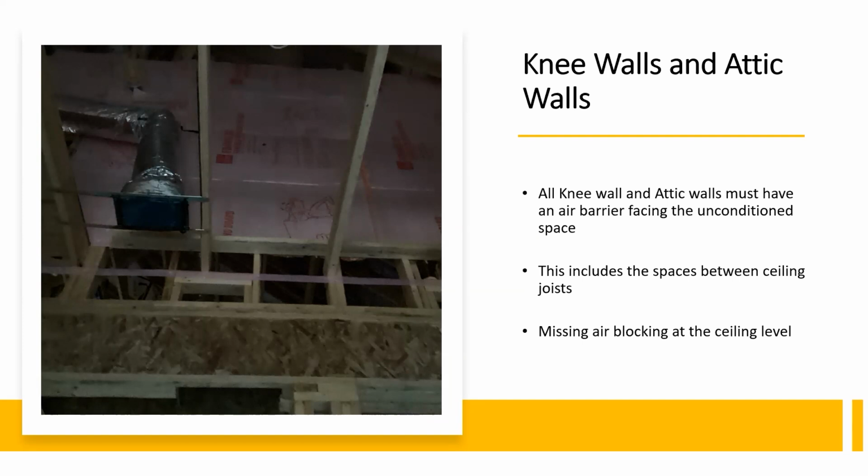Otherwise, we'd see insulation laying up against that on part of that lower wall on the ceiling area between those ceiling joists. But that floating gasket, those guys knew that that was the boundary of the thermal envelope. So they put a gasket up, but no one framed it correctly. So there's nothing stopping air going from those points all the way up into the cavity that's inside, facing adjacent to a conditioned space. Blocking needs to be added directly behind the gaskets, and then all gaps in that blocking need to be sealed.